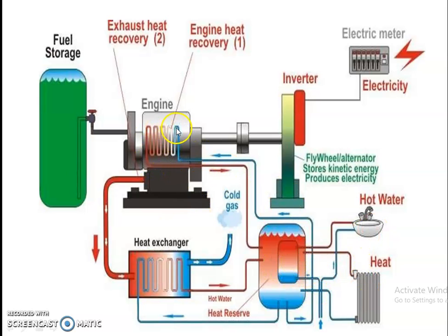And we have also dealt in detail with how to utilize the exhaust gas. Nowadays, because of pollution formed from the exhaust gas, such as unburnt hydrocarbons, carbon monoxide, and oxides of nitrogen, we use the exhaust gas recirculation unit, EGR. EGR is of two types: hot EGR and cold EGR. In hot EGR, the hot exhaust gas is directly entered into the inlet manifold, again to dilute the emission.